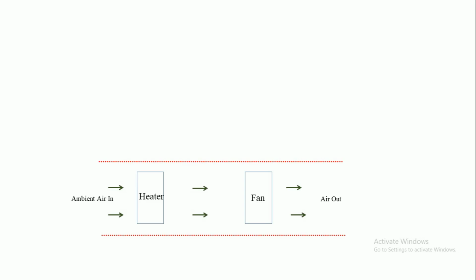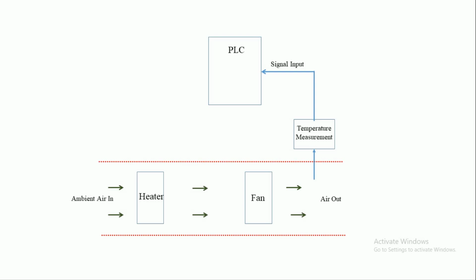of the thermal chamber. For maintaining the chamber outlet air temperature at the target value, first measure the temperature of the chamber outlet air and get a signal to provide to the PLC input. Depending on the existing temperature measurement and the requirement of outlet air temperature, the PLC makes an analog output signal to regulate heater power.